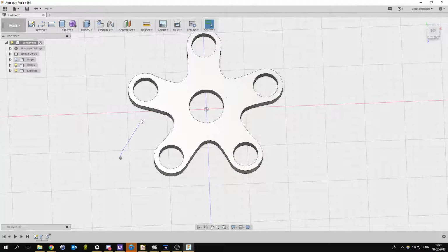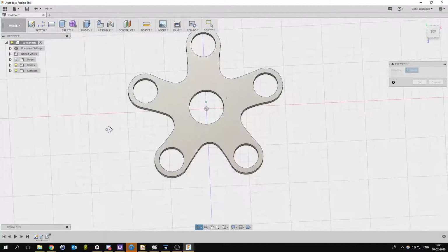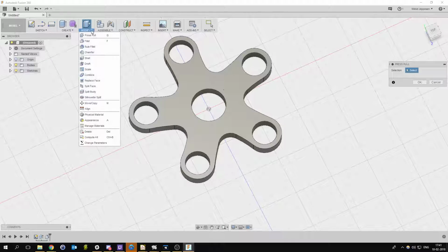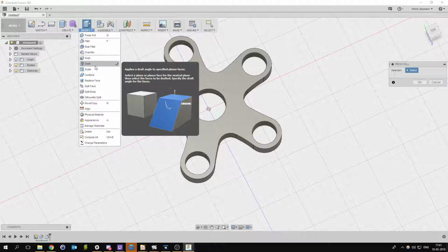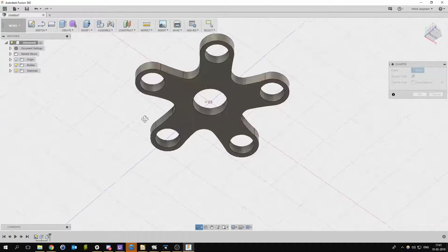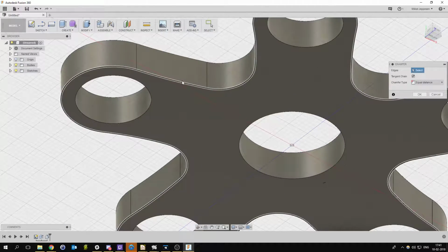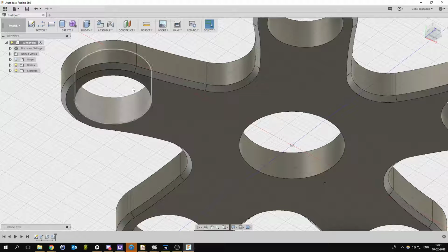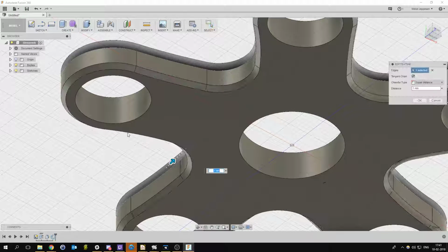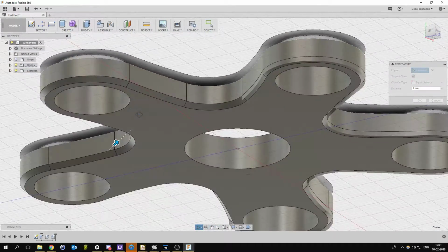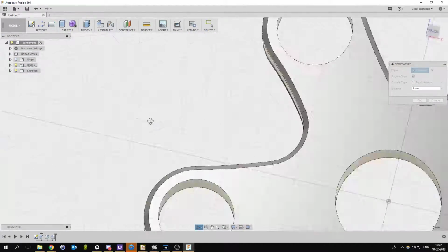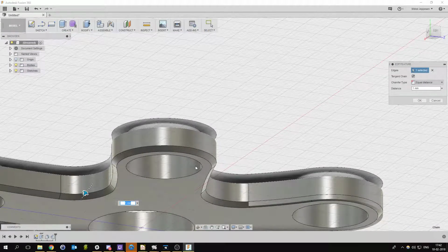So then once you have that, what you can do is say modify, let's add a chamfer at the bottom. Oh, it's reversed scrolling from what I'm used to. This makes it, in my experience, better to print. It kind of gets rid of the problem that you sometimes have with the first layer squeezing out past. I don't know why I can't pick that line.